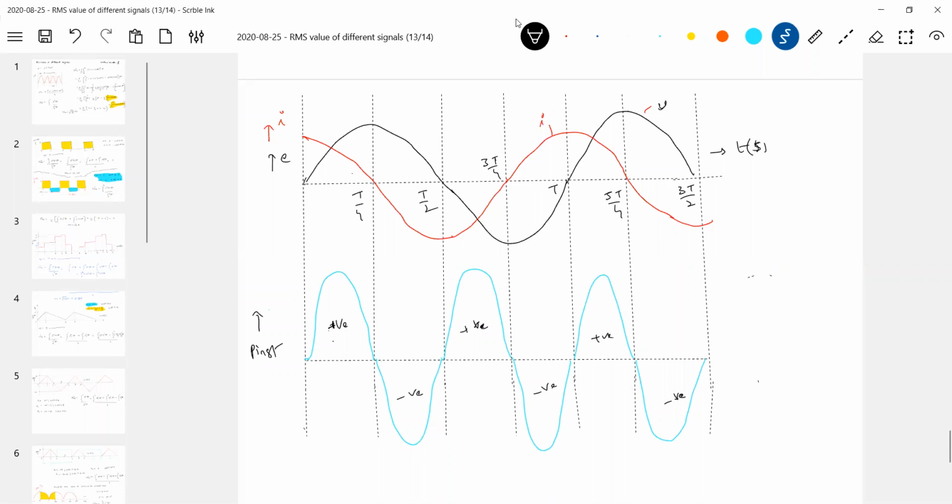So in one cycle, what actually happens? There'll be exchange of energy between the capacitor and the AC source. Altogether, how much power it has drawn from the source, that much power it will return back. Don't say consume, better say draws. How much power the capacitor draws during this interval, that much it will return back here. Again it will draw the power from the source, again it will return back.